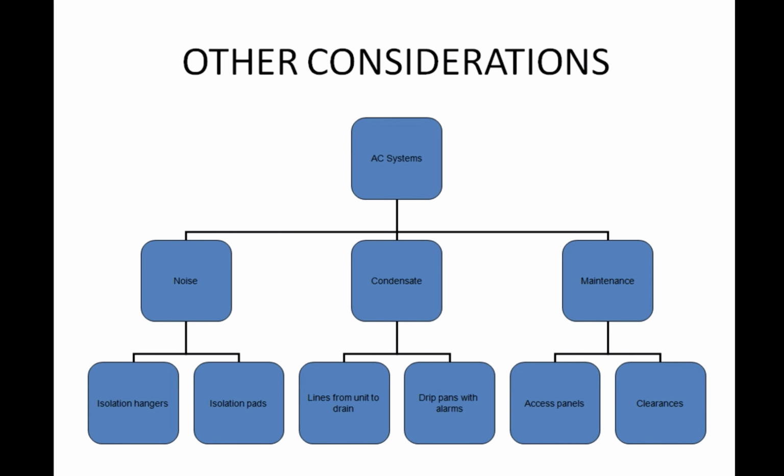All right, so all of that is usually inspected upon maintenance, especially in a ventilation system. Something like condensate can be damaging, in that it could lead to the start of mold or other things that you don't want in your air. That's why you replace the filters often and make sure that you have a way to deal with moisture buildup.